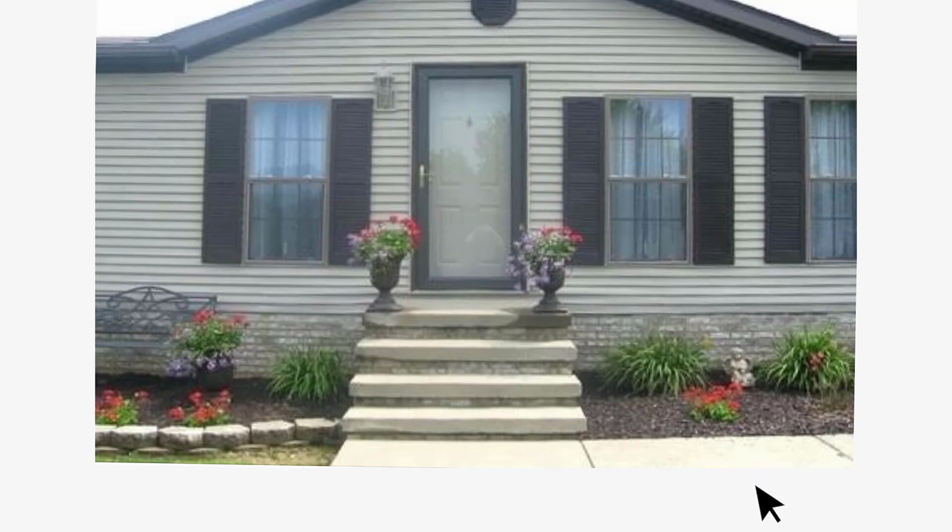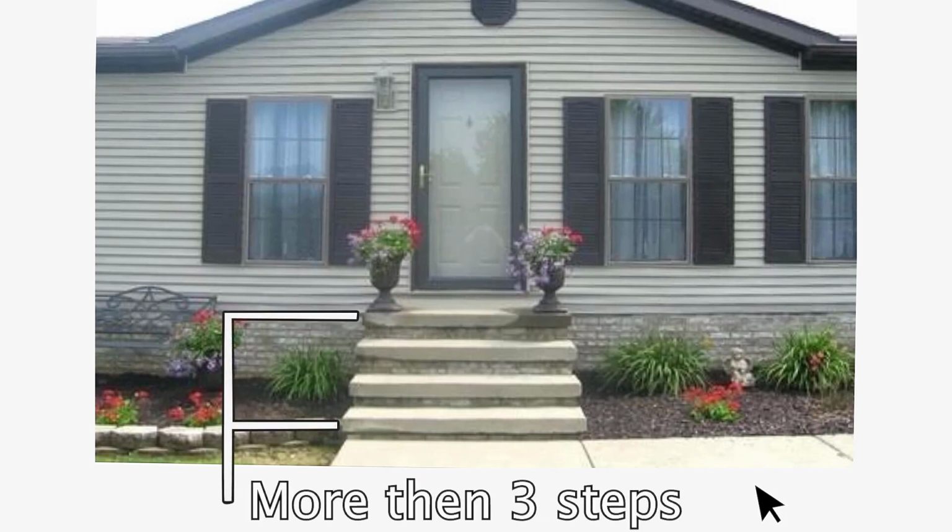So we're going to go into the basics of a cripple wall retrofit. The way you can tell if you have a cripple wall is by the number of steps leading into the front door, or back door if you happen to be on a hillside. So if you have more than 3 steps, you probably have a cripple wall.